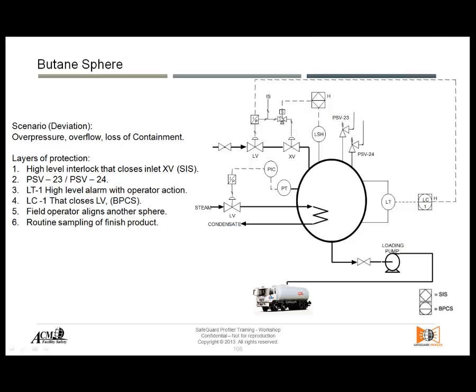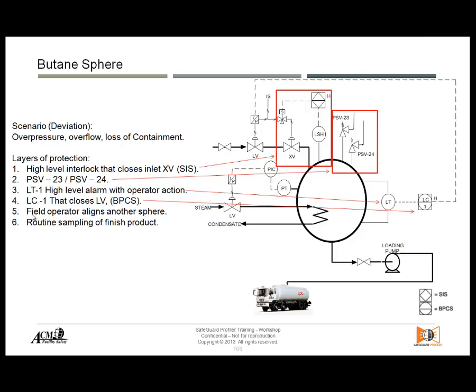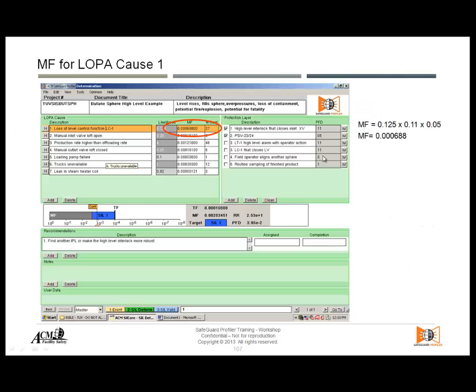So they decided that they needed a safety instrumented function, and now we're going to verify whether that safety instrumented function has the correct amount of reliability, or if the performance is enough or not. And here are listed all the other recognized or accepted safeguards by the hazard and probability study team. So they decided these are safeguards, right?